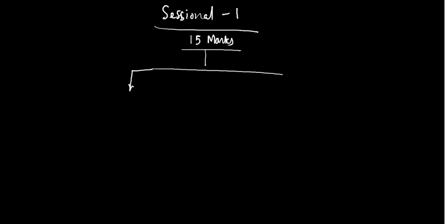We have seen 5 variable K-maps, and the 5 variable Quine-McCluskey method. The Quine-McCluskey method has some procedure, like binarization and grouping of all the min terms according to the number of ones they have. Parity, we have defined the funda of parity, number of ones. Then we have also verified them. We have designed some problems, and in today's lab also we are going to design such circuits.